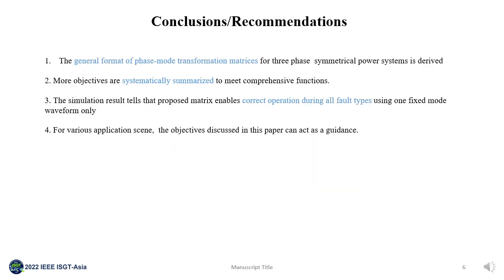Here are some conclusions and recommendations for this paper. This paper comprehensively presents the general theory of phase mode transformation matrices for three-phase symmetrical power systems. Specifically, the paper derives not only the basic conditions to ensure complete decoupling, but also the extra conditions to meet additional objectives to simplify the design of protection and fault location. After that, a matrix which enables correct operation during all fault types using one fixed mode is proposed and verified.